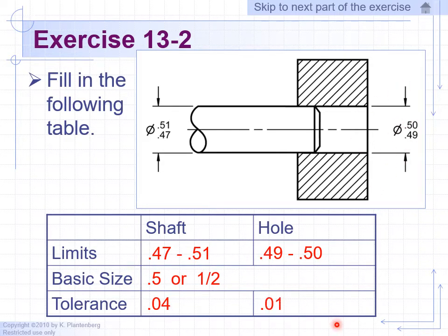And for the hole, we're giving them a tolerance or wiggle room of 0.01, so we just subtract 0.49 from 0.50 and we get 0.01. That's the wiggle room we are providing to the machine shop for the hole diameter. So here we're basically telling the machine shop, yes, we are aiming for a 0.50 or half-inch diameter, but 0.50 is the max. On the low end, you can be off by 0.01. We can be off by as low as 0.49 in diameter, but the maximum acceptable is 0.50. We cannot go beyond 0.50 in this case.